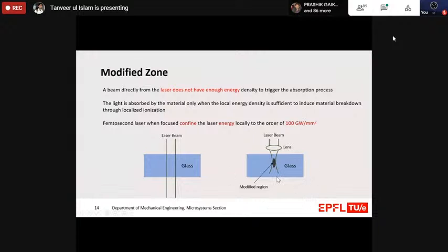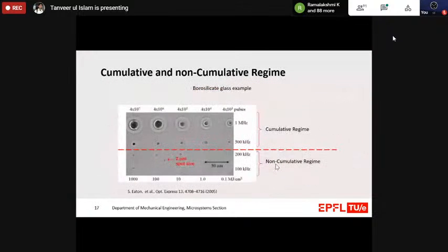Now, the reason why the spot is in an elliptical shape is because once the laser hits the target, plasma is generated, like I showed in one of the graphs, where different phenomena happen in a very short time interval. Once that plasma is generated, it further concentrates the light into itself, and that allows the distribution of energy more in the Z direction than in the XY direction. So apart from the objective lens that we use to focus the laser beam in a substrate, when the plasma is generated, that itself acts as another lens, further concentrating this energy in a very small and narrow area. This way, we are able to go down to a size near the wavelength of the laser, but then we can have this effect on a larger area either by increasing the number of pulses or by scanning to different areas of the substrate.